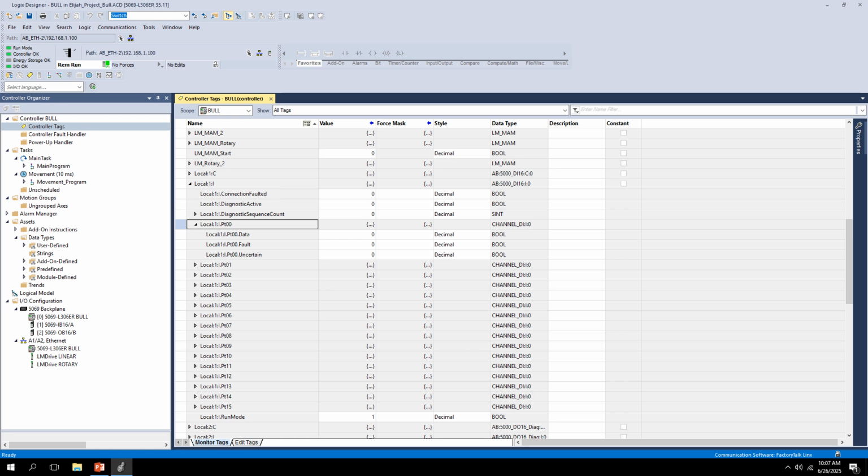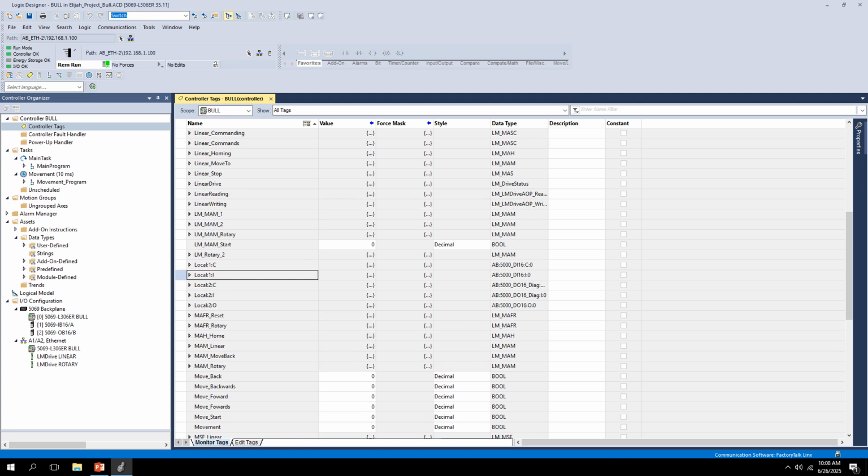So if I go over here, I put my hand in front of the laser, boom, you can see it go to 1, take my hand away, it's 0, put my hand in front again, you're getting 1, and again, took my hand away, you get 0. So this confirms that I've connected my photoelectric sensor right to the 00 slot, because you can see obviously the data is going from the false state to the true state, and this is going to help you understand how I got this to work.